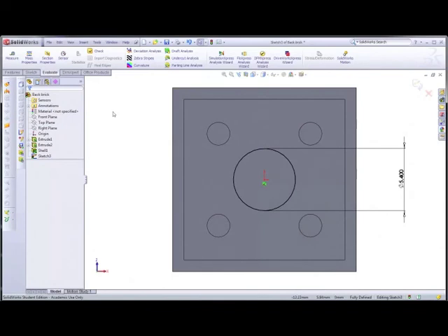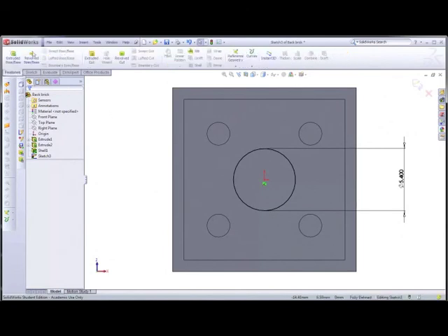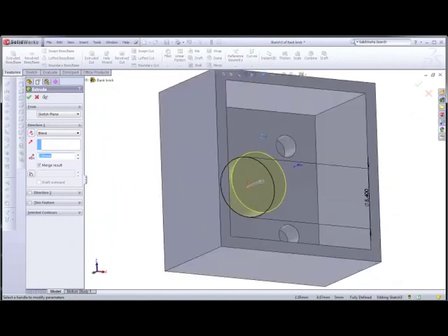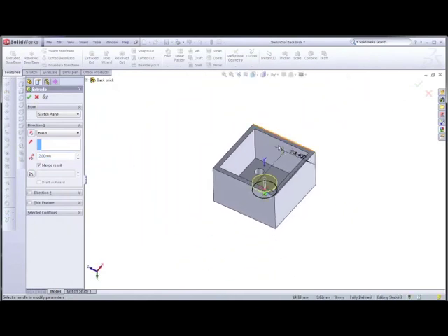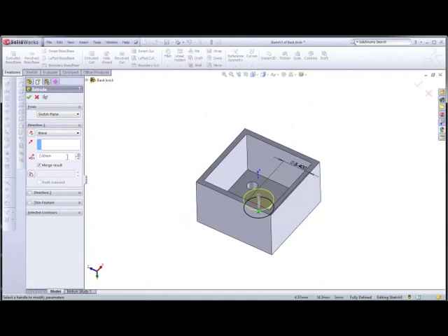Now, I'm going to show you, there's 2 ways of doing this. In this one I'll show you the slightly harder, longer route, but it's good so therefore you can get to see the cut tool as well. So what I'm going to do first is I'm going to go Feature, extrude this up, okay, so extruding the same way as before. Up 9mm, so green tick that.